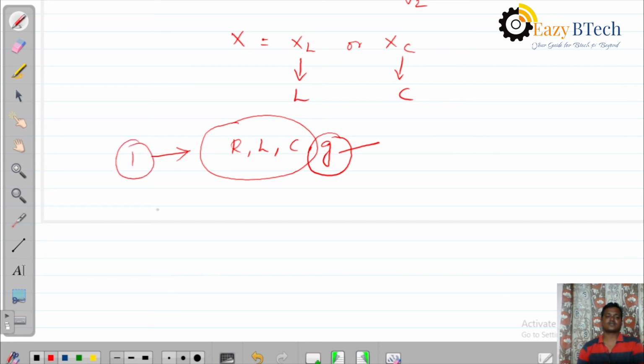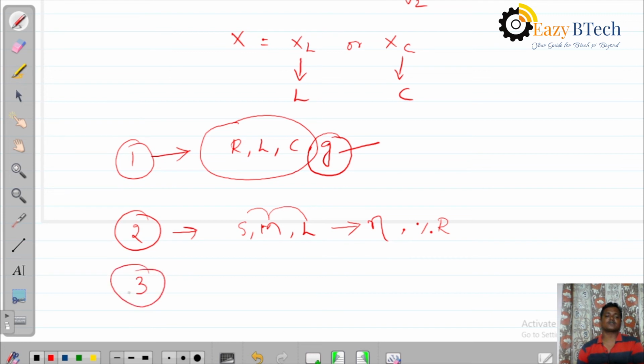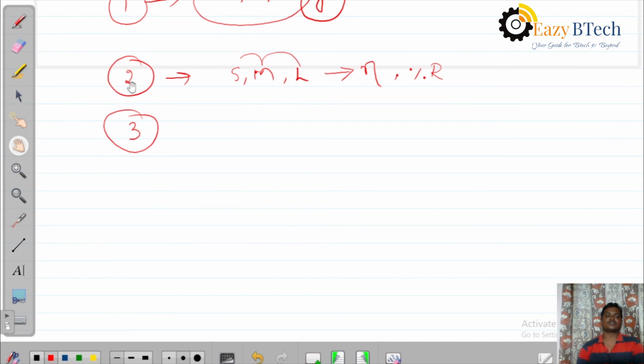That is the first concept. And the second concept is classification of transmission lines. The transmission lines are classified into short transmission line, medium transmission line and long transmission line. On what basis the transmission line is classified, and how to evaluate the performance characteristics of transmission systems, that is calculation of efficiency and regulation of that particular transmission system. That is the second one, and the third one is the mechanical design of the transmission system.